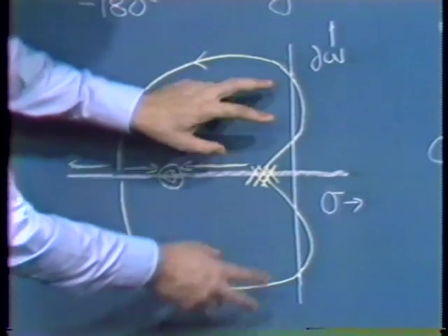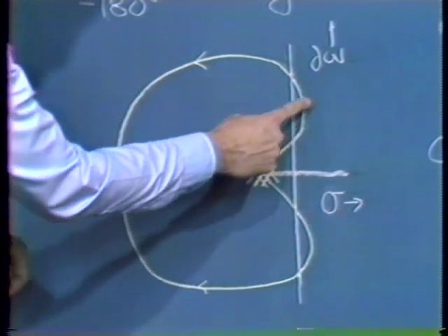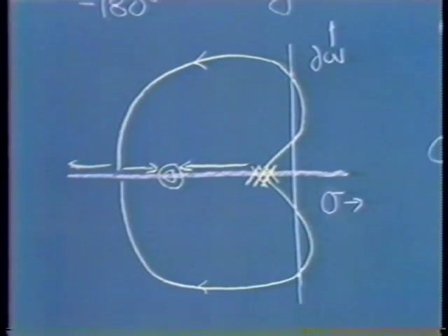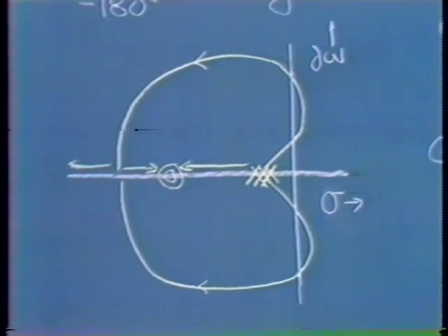There'd be an intermediate range of A0 F0 product where 2 of the system closed loop poles lay in the right half of the S-plane. Consequently, the system is unstable. And then for still higher values of the A0 F0 product, once again, all 3 branches lie in the left half of the S-plane.